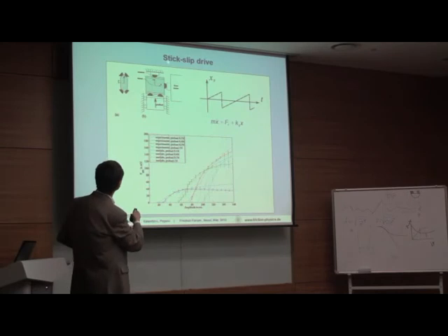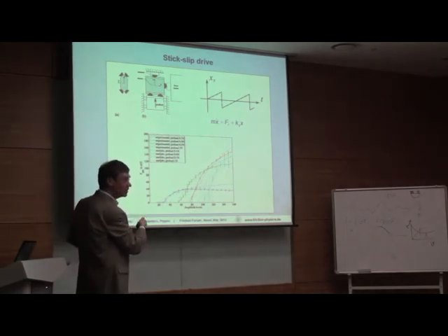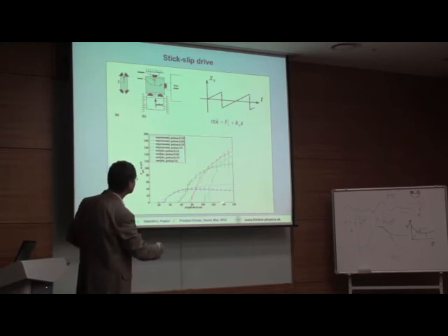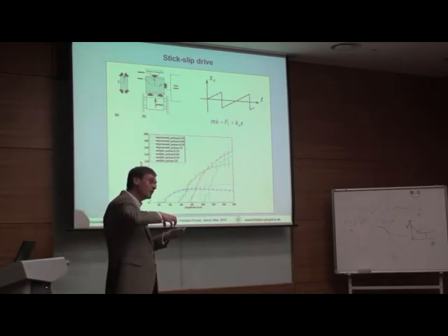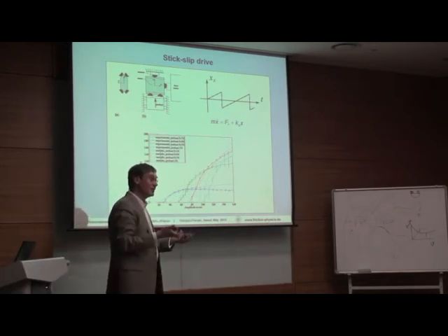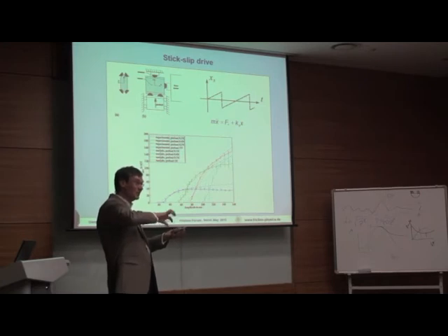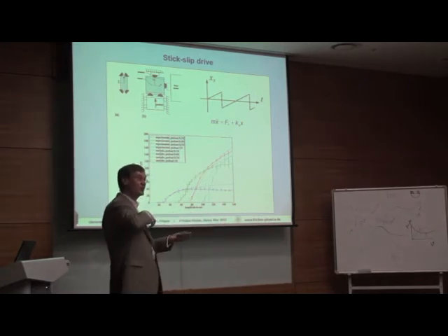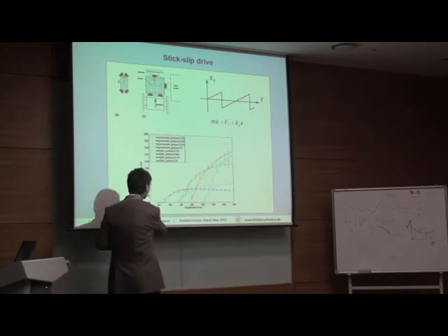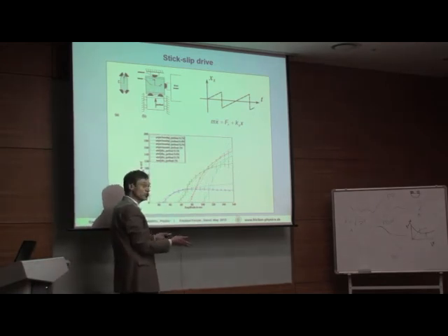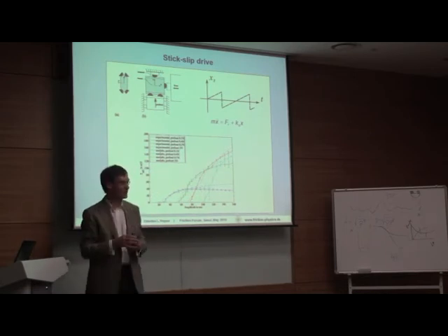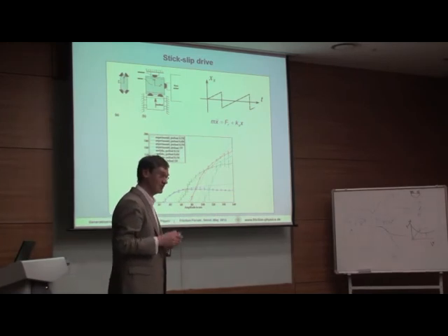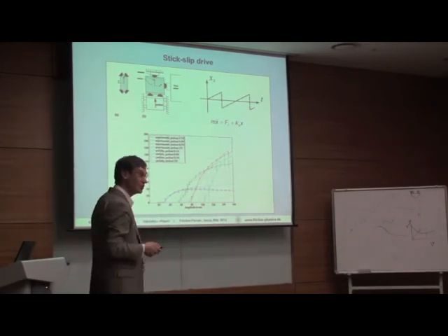And you can measure the force which you have here, the generated force, and this is the amplitude of the oscillation. And of course, if you have amplitude smaller than this slipping, then you have nothing. You just move it back and forth, and you have to slip in one direction. So you have some amplitude after which it starts to generate the force. Before this, you can see here how good is the model, this zero amplitude, this preliminary slip.